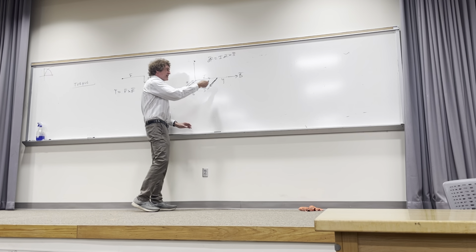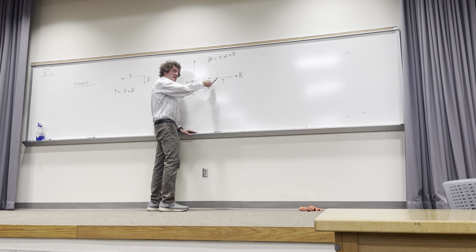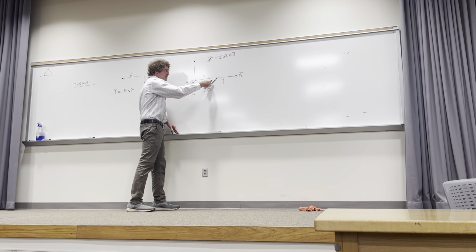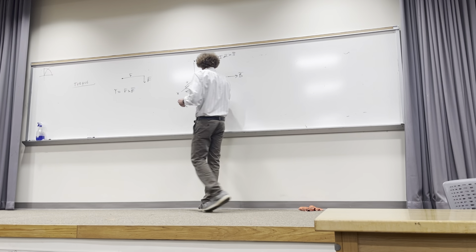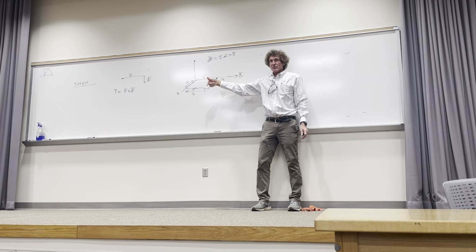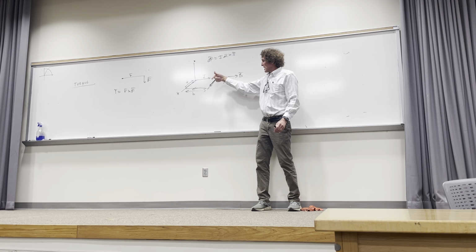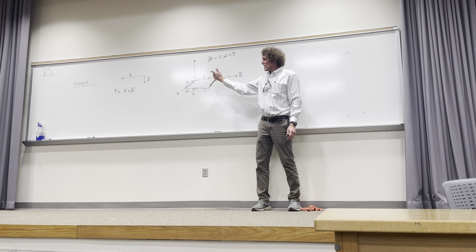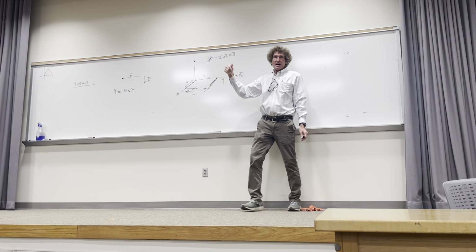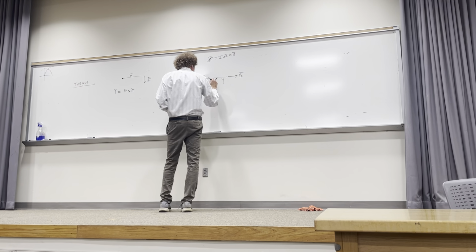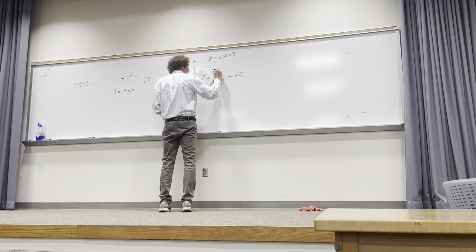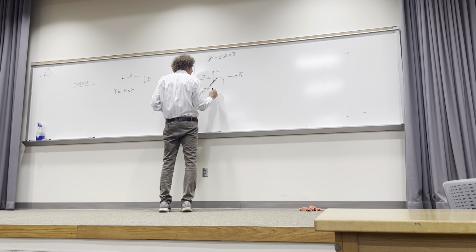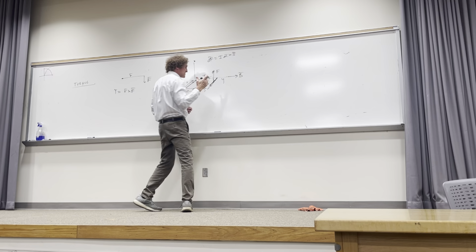If I have I dL in the AX direction, on this member here, which way is the force? I've got the B field going the Y direction everywhere, it's the same, right? So I've got I dL, think of it coming out, crossed into B is up, AZ. Y'all see it? So that would be the force on this member right here, and it should make sense.